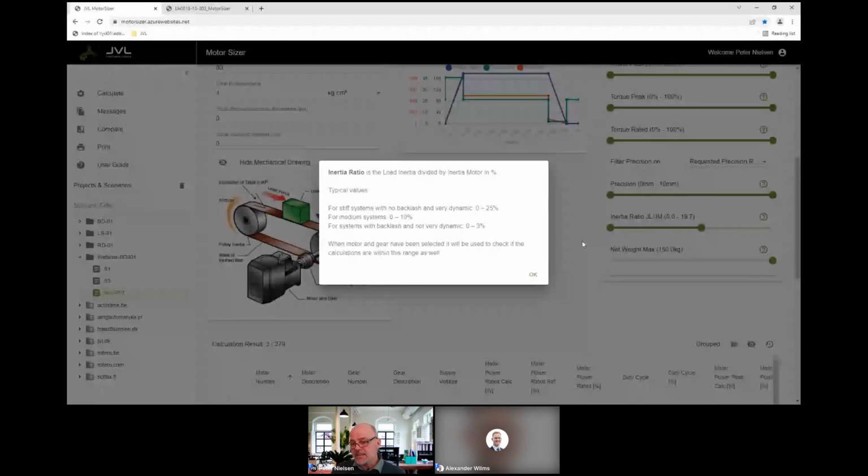Sorry? Yeah, it's difficult to tell exactly for the system you're talking about, because I don't know about elasticity in the belt, for example. I don't know how much backlash you have in the gear. That kind of information should be added. Then we can maybe find out what is possible or what's recommended to use at least. But that's some information. If you have a stiff system where the wheel is mounted, it could be a disc drive where it's mounted directly on the motor shaft, it will be very stiff.